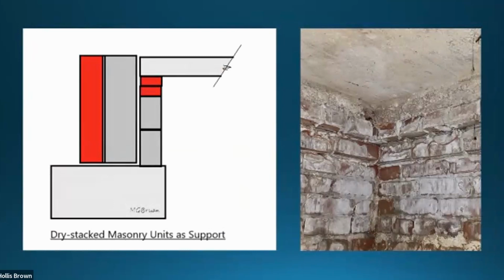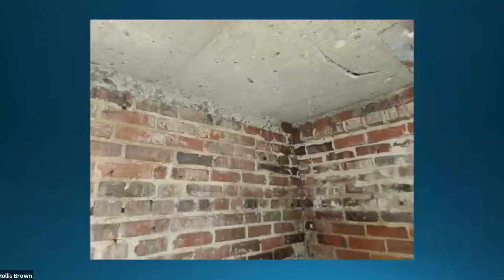But on the right, you see where this is probably a 1940s house, and they were brilliant enough to know that you needed to corbel out a couple layers of brick to catch the concrete, and so that concrete is fine. Some of this is just pure laziness. Of course, the builder knows that what I'm saying is true. They just refuse to do it.